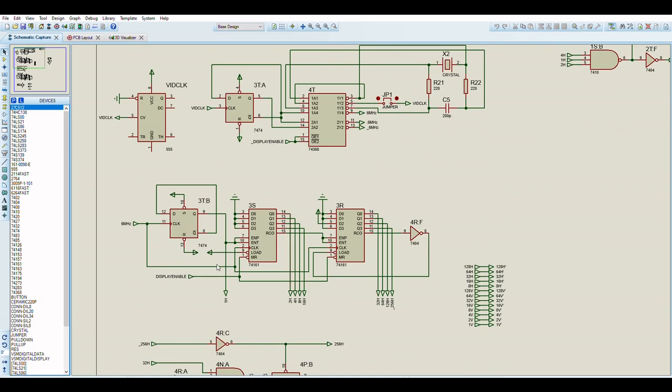So the 6 megahertz clock comes in here, and what we have as an output is 9 bits worth of horizontal clocking information. Interestingly and usefully, the least significant bit uses the output from the flip-flop, which is as you would expect, because then the next 8 bits come from 2 clocked counters.